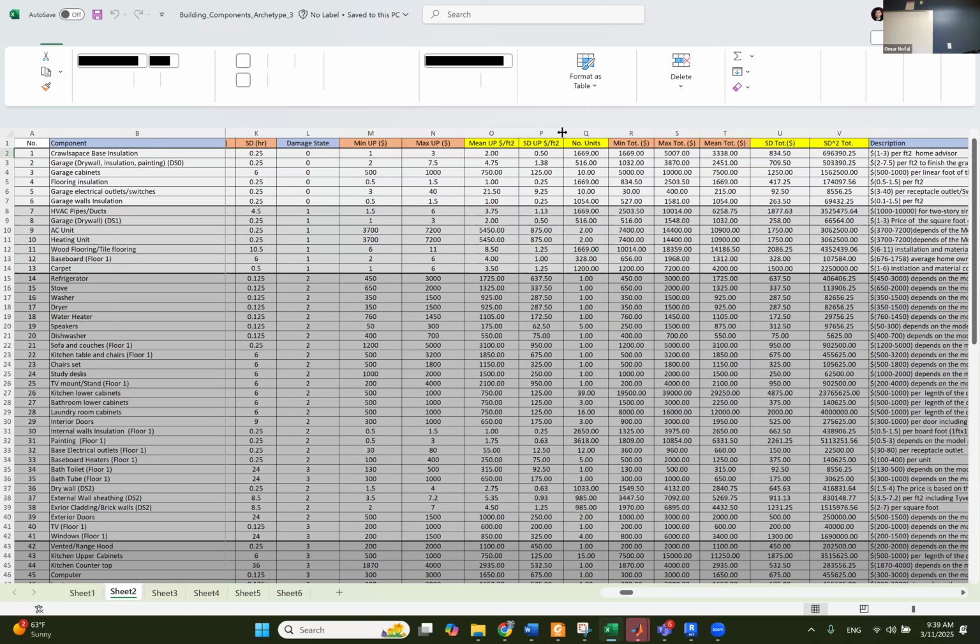But if we're talking about elements that are linear foot, like pipes, then I have how many linear footage. If it's a flooring, how many square footage. If it's a drywall, how many square footage. So I have to use Revit to find out what these footages look like. Once I found how many units I have, I can find the minimum price and the maximum price by multiplying the unit price by the total quantity. Like if I have pipes that are, let's say, 100 foot, and the price per linear foot is like $10, then 100 times 10 is $1,000, the total cost of the pipes.